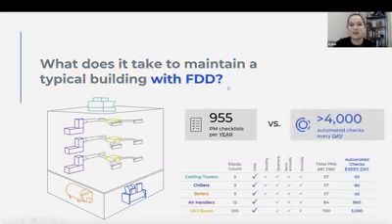So the foundation here is that with FDD, you can supplement some of those PMs that maybe you're not getting done, or you can make decisions about how much of your PM to perform and when to perform them. If your FDD system can perform checks on each of these pieces of equipment, that would sometimes supplement some of those checklist items on your PM, and potentially take the place of them. On top of that, by running FDD against systems, you may not need to PM certain pieces of equipment.